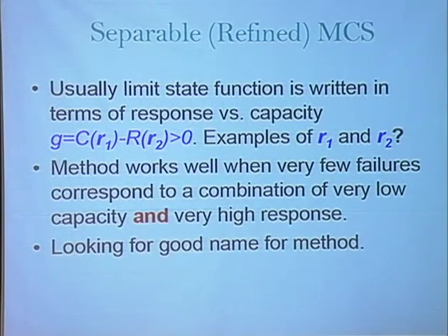Process. Yeah, so the processing is not likely to change much the stresses, but it's likely to have a large effect on the capacity. What variables have the strongest effect on the stress? What random variables have typically the strongest effect on the stress? Geometry and loading, right?